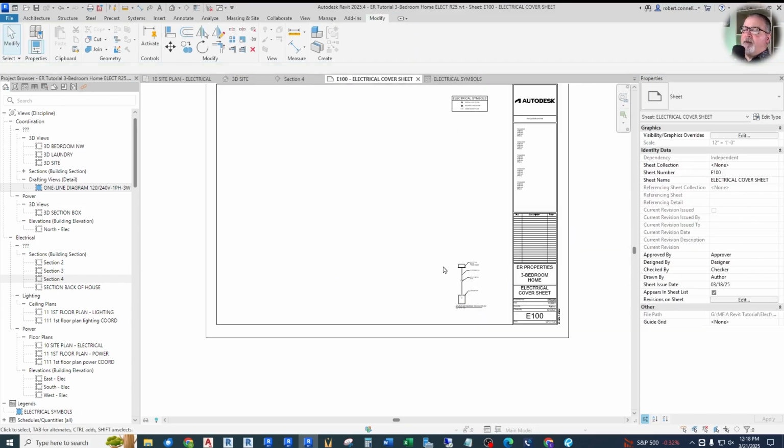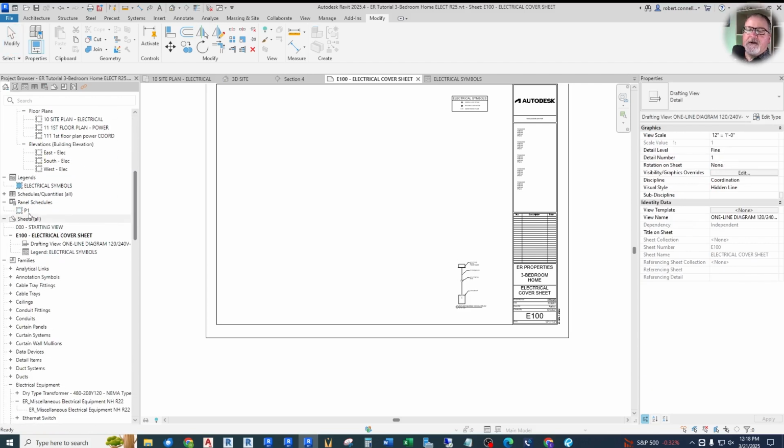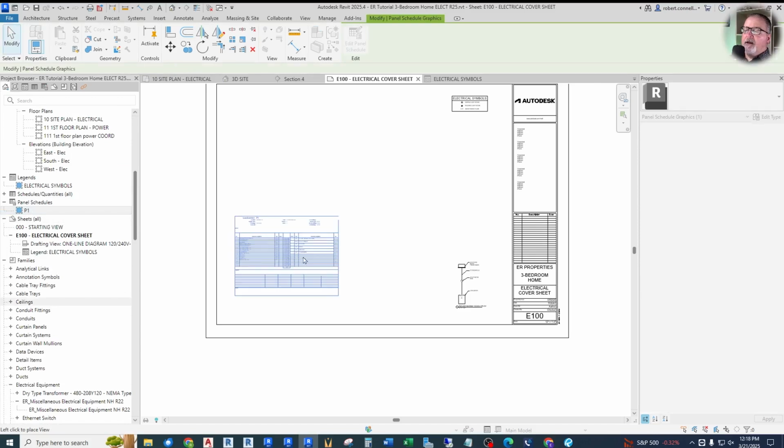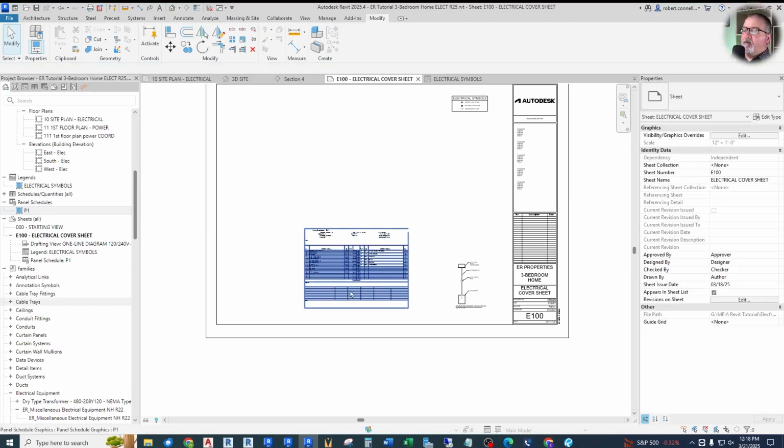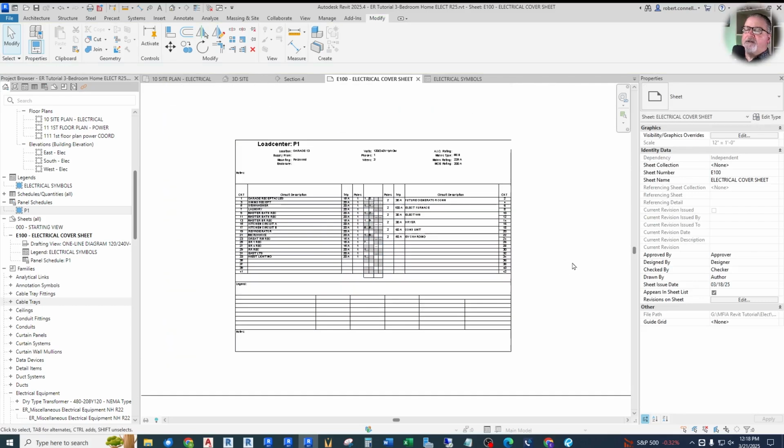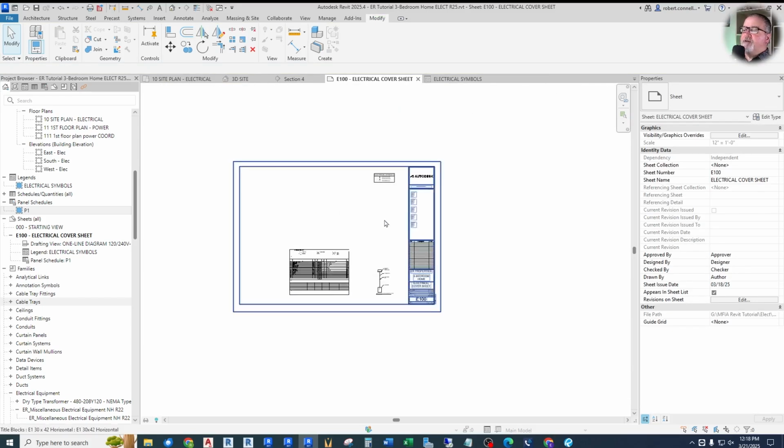And then I want to get the panel schedule on this sheet. So where's the panel schedule? Down here. Let's drag it on, let go. There it is. And we'll put that right here. And there's our panel schedule. But that's the basics of getting those onto your sheet.